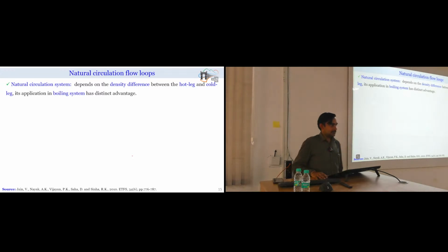From the Kelvin Helmholtz point of view? Yes, Kelvin Helmholtz, because whenever the value of critical heat flux is predicted, that is based on the Kelvin Helmholtz instability only. So the ideal condition would be in that heat exchanger everything gets converted, right? Yes. And so you say sometimes the mist will be there. Yes, that is not the ideal condition. So it means that if we have to fully convert, where our bulk enthalpy is becoming equal to that of saturated vapor enthalpy, after that point also we should keep on heating to some extent in order to get the completely pure vapor.